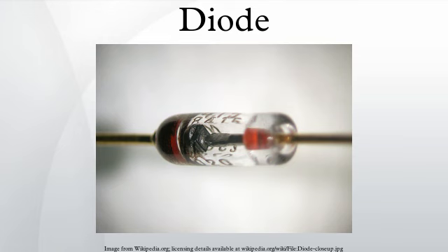Junction diodes, PN junction diode. A PN junction diode is made of a crystal of semiconductor, usually silicon, but germanium and gallium arsenide are also used. Impurities are added to it to create a region on one side that contains negative charge carriers, called N-type semiconductor, and a region on the other side that contains positive charge carriers, called P-type semiconductor. When two materials, that is N-type and P-type, are attached together, a momentary flow of electrons occurs from the N to the P side, resulting in a third region where no charge carriers are present. This region is called the depletion region due to the absence of charge carriers.